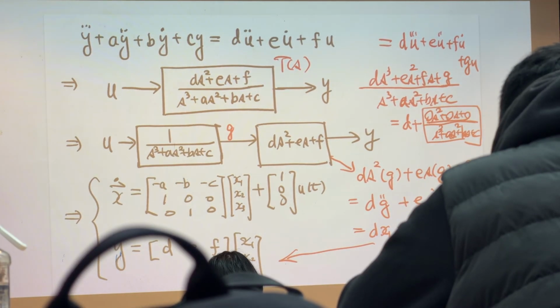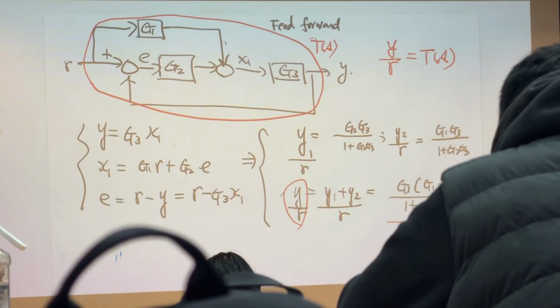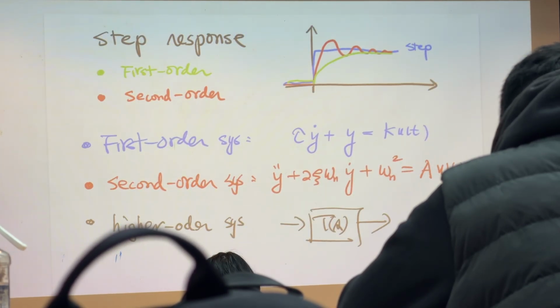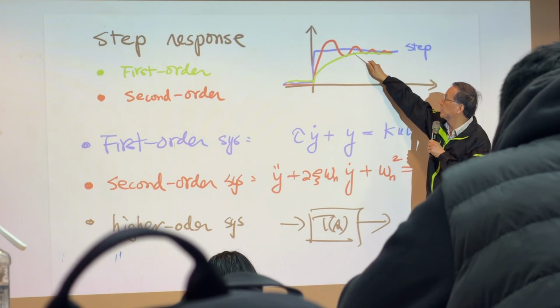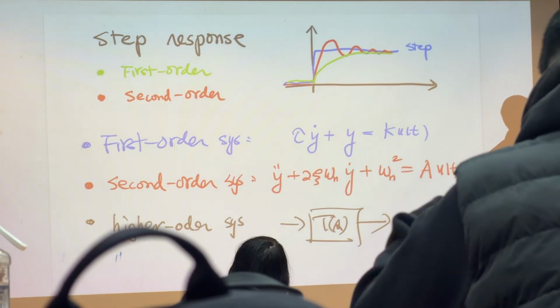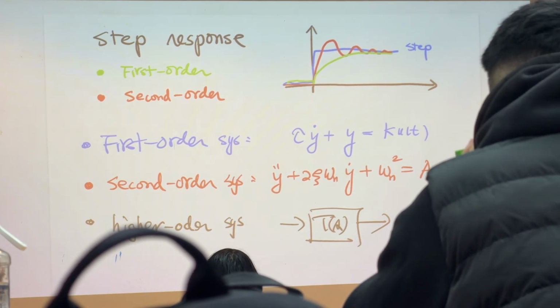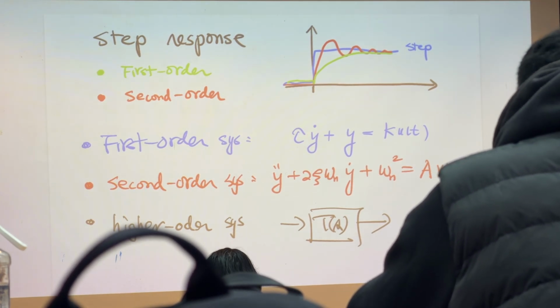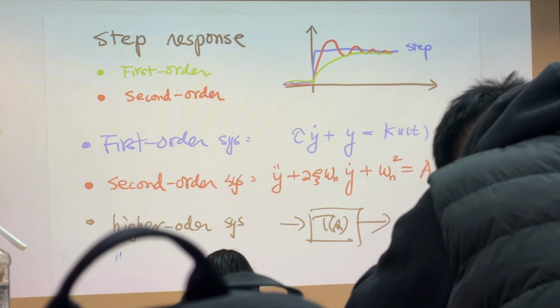Multiple axes are all fine, okay? Then you use this to simulate this process. Even for a higher-order system, you can still generate the step response, and you will know where the position is at that point. So we can use this to simulate the machine tool movement or simulate a robot movement. Okay? Do you understand what I'm talking about?